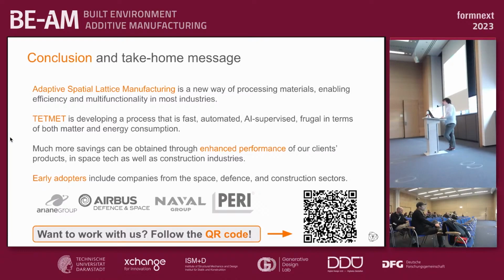Of course, if you weld and re-weld a node, you will change the phases in presence, you will change the properties, but so it happens in additive manufacturing. So the worst case scenario is that we are as bad as additive manufacturing, and I think we are much better because we have very small heat affected zones. That's my gut feeling as a metallurgy professor, but this needs actual characterization and confirmation, and we are working on it at the moment.